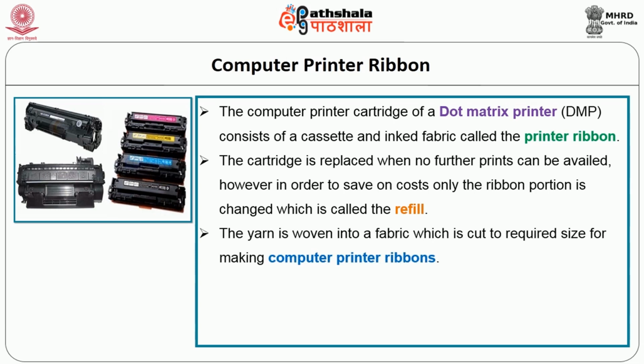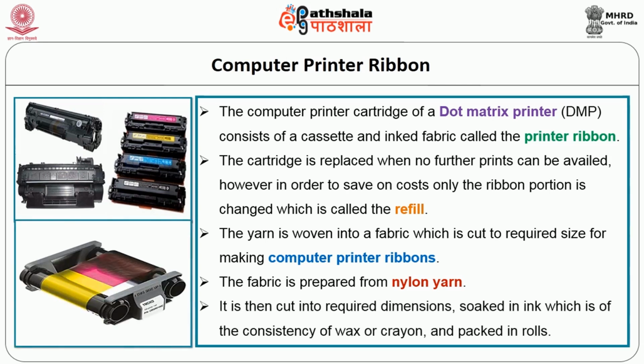The yarn is woven into a fabric which is cut to required size for making computer printer ribbons. The fabric is prepared from nylon yarns. It is then cut into required dimensions, soaked in ink which is of the consistency of wax or crayon, and packed